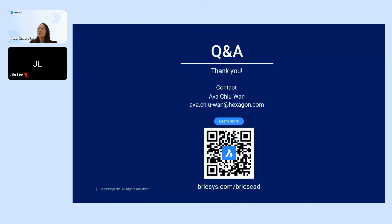Any option to get optimum earthwork calculations? So far, the workflow process that we have here in BricsCAD is creating your TIN surface, of course, as accurate as possible, and then you have the option of rounded edges or cornered edges for your volume surfaces or grading pads. Then you use your two TIN surfaces to compare them and find the difference, which is the volume surface.